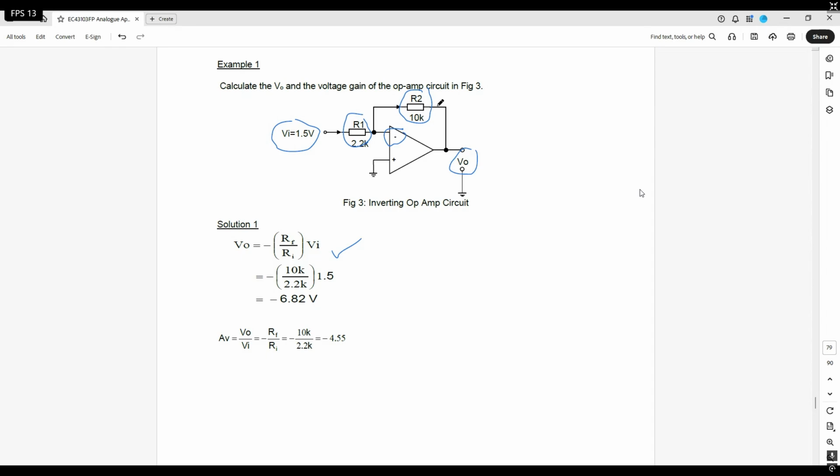All right. This is a feedback resistor. R2, don't confuse. Because if you put R1 as the value, then the whole equation, or rather the answer, will be wrong. So R2 is the RF, which is seen here. They put RF. So remember, RF is a feedback resistor. And then Ri is the input resistor, which is R1 over here. So 10K over 2.2, very obvious.